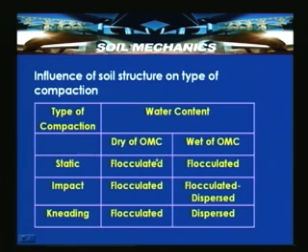That means whatever energy is applied in static compaction, the structure remains flocculated both on the dry side of the optimum and the wet side of the optimum.